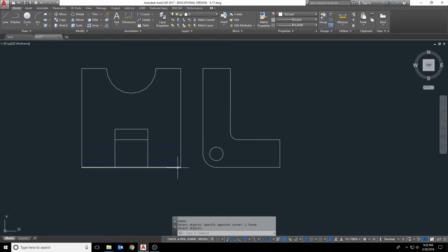In the location of this, it tells us that it is 0.75 over to here, and then it says that this section right here is a dimension of 1. That is going to make it very much off-center, so we're going to change that dimension of 1 right here to a dimension of 0.75. That way everything is nice and symmetrical. And we also are missing the dimension for the length of this segment right here, which we can make 1.75. And with that, this object will at least look like it's supposed to in the book.